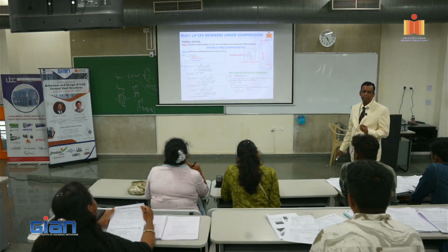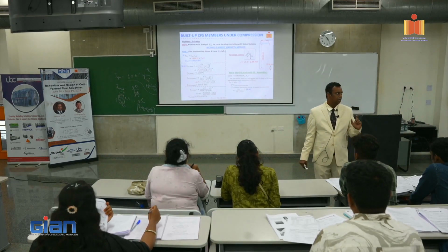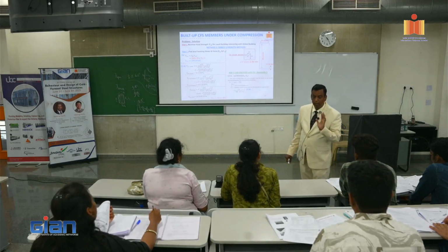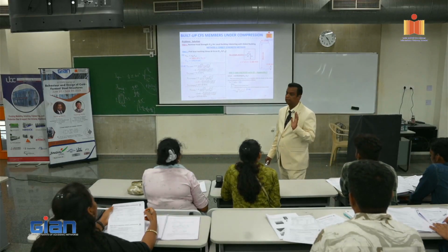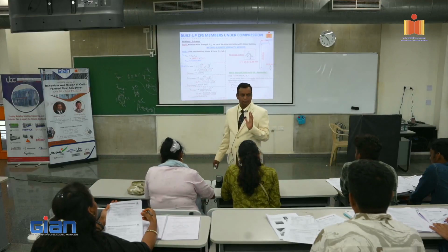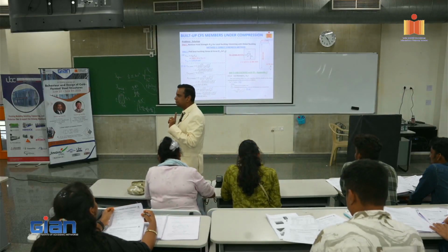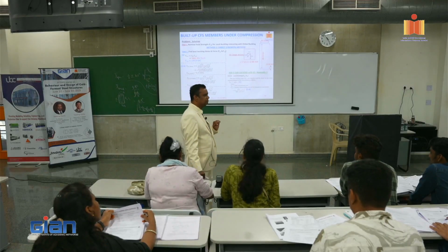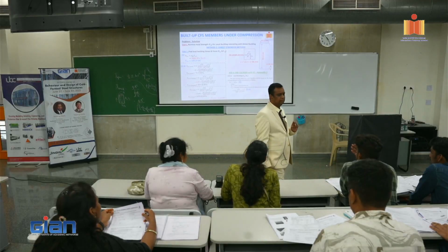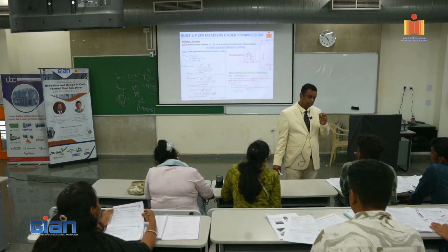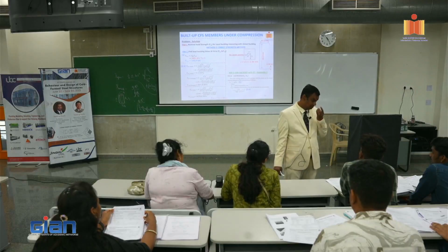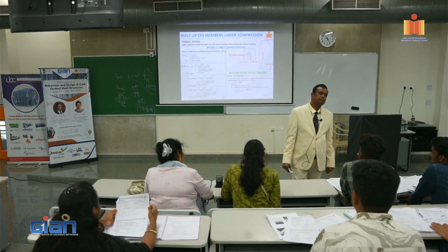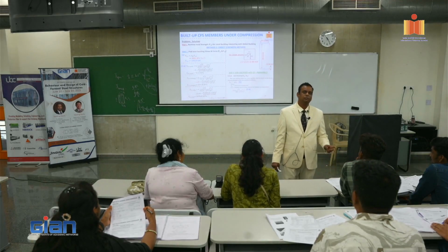So PCRL is the critical local buckling load. Now let me ask you, what is the difference between the effective width method and DSM? In the effective width method, we reduce the area instead of reducing the stress. DSM will reduce the stress and keep the area the same.